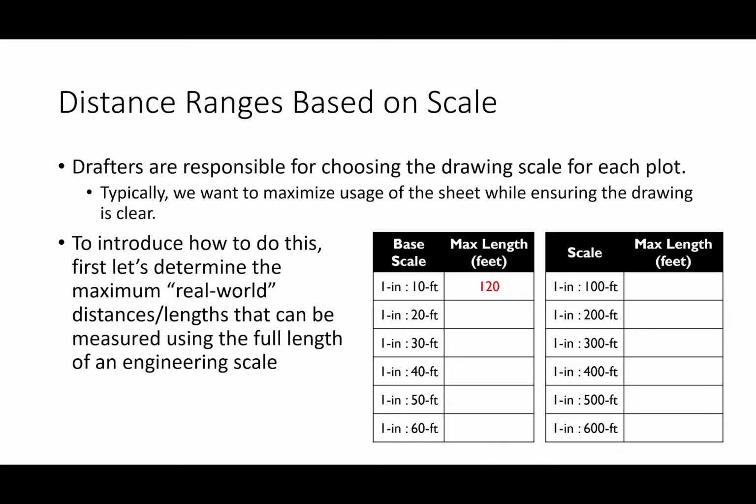So what would it be for 1 inch equals 20 feet? 240, okay? Everybody getting the idea? 240, 360, 480, 600, 720, and so on and so forth. What if 1 inch equals 100 feet? What's the longest distance I can measure? 1,200 feet. That's exactly right. So you're all getting the pattern. I want you to keep this thought process in your head, because right now I want to give you an example of how this would work.